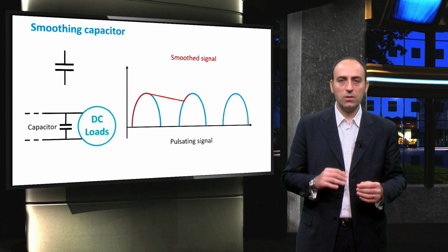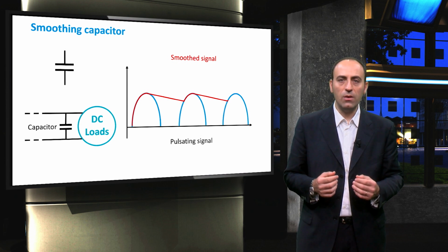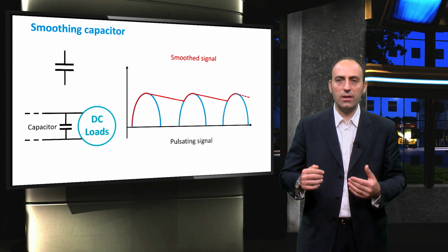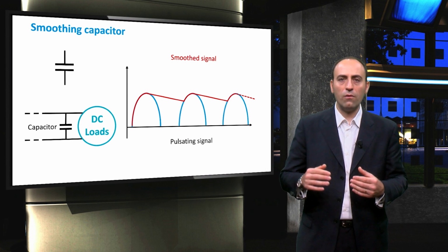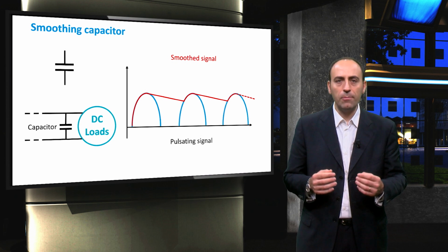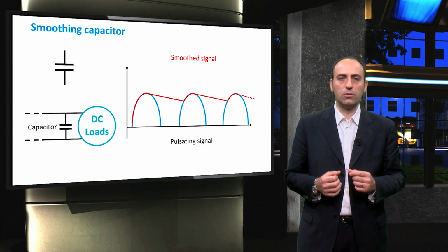When it reaches the peak of the signal, the capacitor is charged to its peak value, and here the role of the capacitor is evident because it starts to release the stored energy. So in this short gap of time, the continuous flow of current gradually moves to the next periodic pulse, filling the gap and allowing the load to be powered at all times without any interruption.